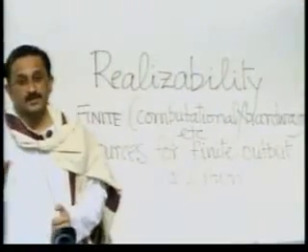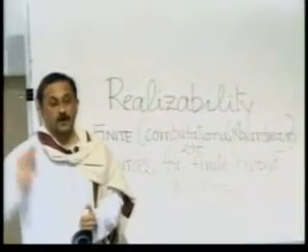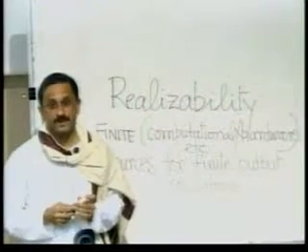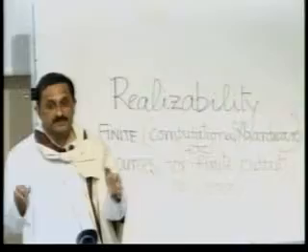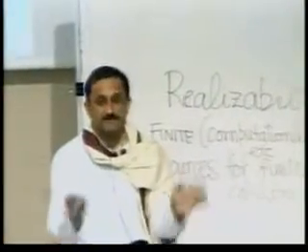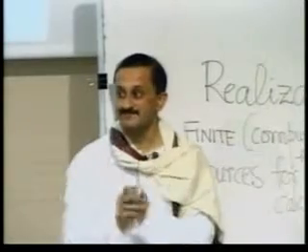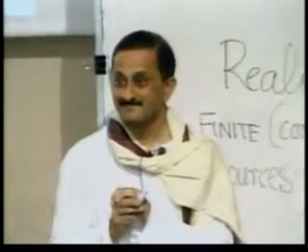By finite output calculation, what do I mean? Calculation of the output over a finite range of the independent variable at the output. So if you have a finite range of the independent variable at the output, the amount of resource that you need to invest to obtain that output in the realization of the system must be finite. Then you say the system is realizable. In fact, there are many LSI systems that are not realizable, or at least whose realization is not known to date. We can approximate them, but we cannot realize them exactly. That's the paradox of LSI systems.